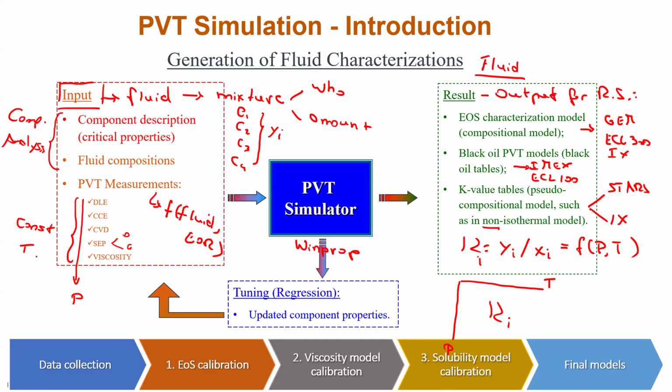And if you have oil from the mud and oil from the reservoir, this mixture doesn't represent the in situ fluid of the reservoir. So sometimes you need to neglect some data because those data are contaminated by drilling mud.